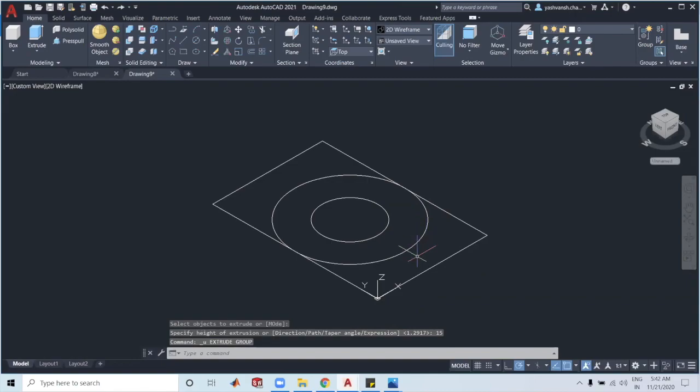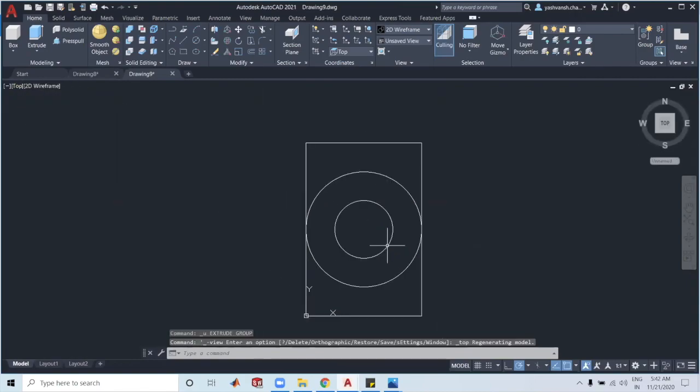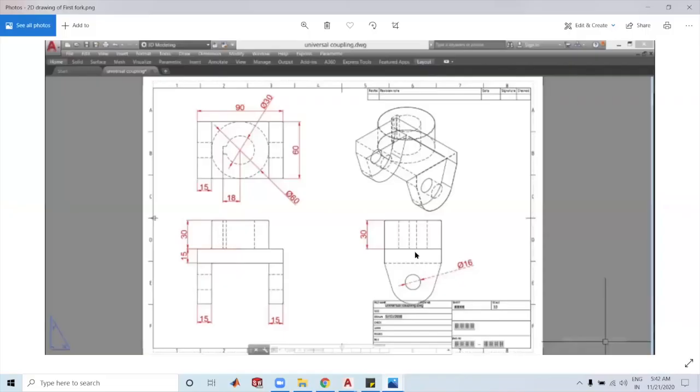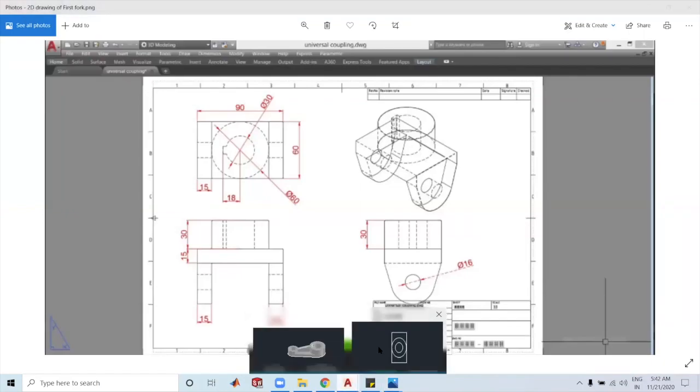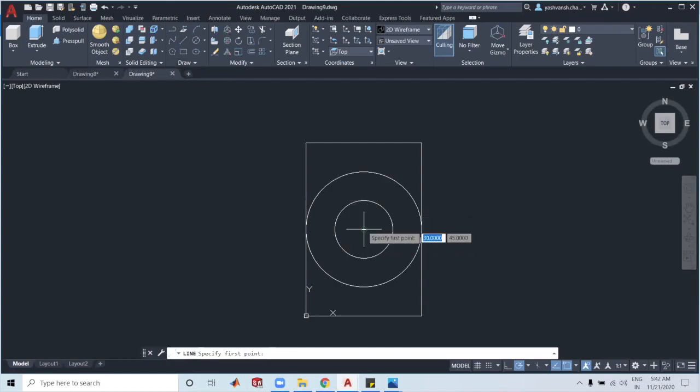Before doing that, I just wanted to show you something. You see this key over here, I'll just make that. Select the line command from the draw tab again, look for the center point, and draw a vertical line downwards of 18 units.